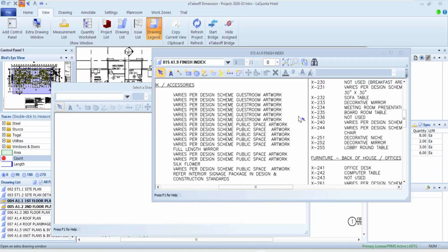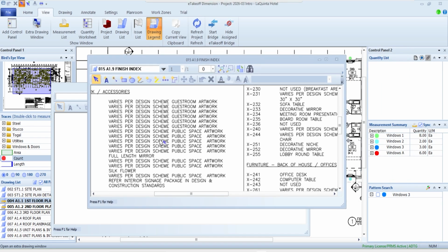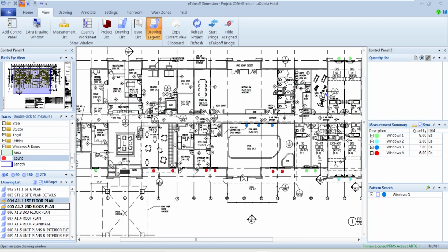So in this case here, I've really got 3 different windows going on. I can have my floor schedule on one and my wall schedule on another, and where I'm doing takeoff on my main screen and so forth, all that right in front of my face as I'm doing takeoff. And then I can also add notations from any of them if I want to put myself some reminders or put a note, maybe I've got a question for an architect that I can put a note on and take a picture and send it to him or something like that.